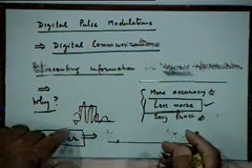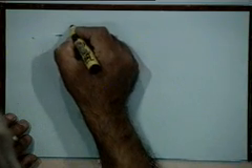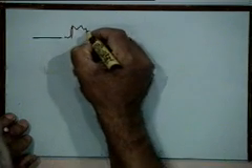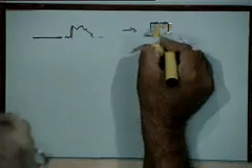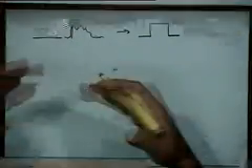in the sense that you have to clean up the pulse and transmit a fresh, absolutely clean pulse once again. As the signal propagates, it becomes a little noisy on the way. So, the pulse is distorted like that, and you clean up this pulse and convert it into a pulse like that by a very simple matched filtering and clipping kind of operation, and then retransmit it, and keep doing this regeneration as and when required.